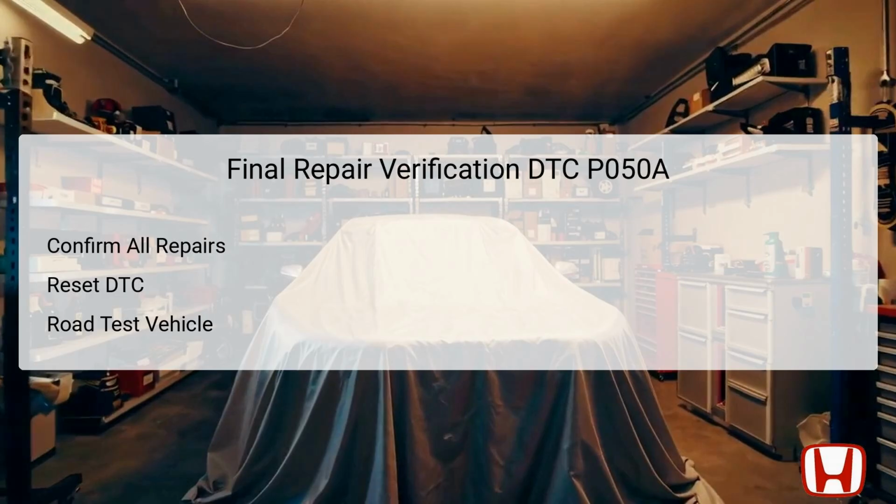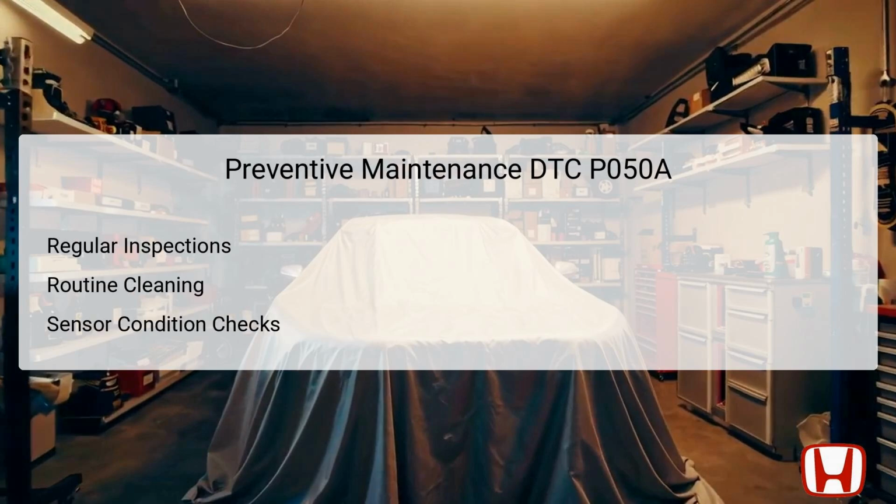During this road test, monitor for any resurgence of symptoms or the check engine light. This step ensures that the vehicle operates within normal parameters and confirms the effective resolution of the DTC P050A error. Preventive maintenance is vital in ensuring sustained engine performance and minimizing the occurrence of DTC P050A in the future. Regular inspections of key components, such as the air cleaner and throttle body, should be scheduled to ensure they are free from dirt and blockages.